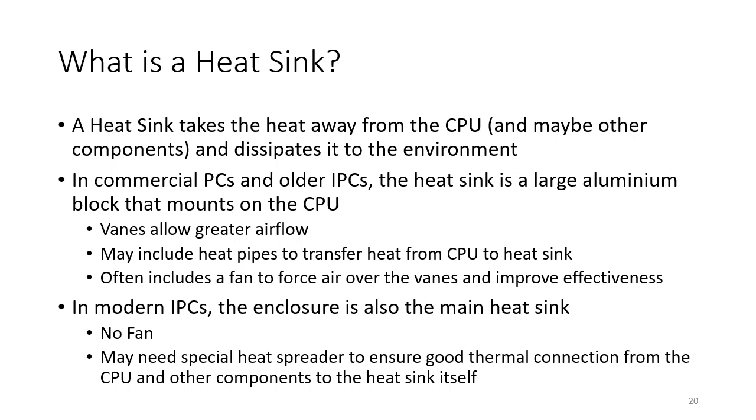Now, in an industrial PC, you probably don't want a fan, but in many commercial applications, you will find a fan. What the fan does is it forces air over the vanes, and that improves their effectiveness rather than just relying on ambient airflow. Now, in modern industrial PCs, what you might also find is the enclosure is also the heatsink. So there's no fans.